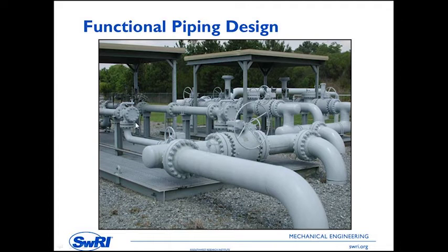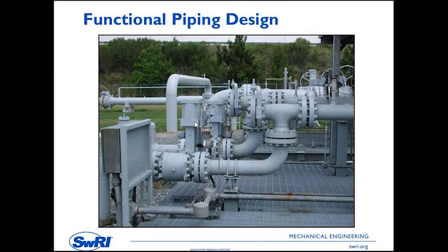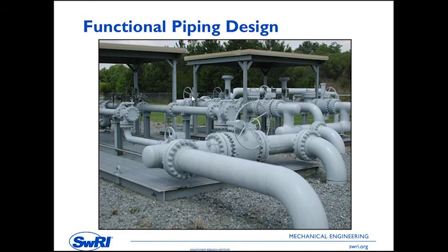Here's an example of an interesting piping configuration. We have a header here that has two mainline feeds coming into it. This elbow and run down to the header. Then we come off with a 4-inch ultrasonic meter and I believe this was a 6 or 8-inch ultrasonic.